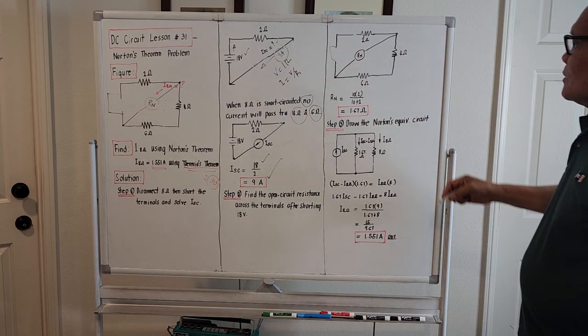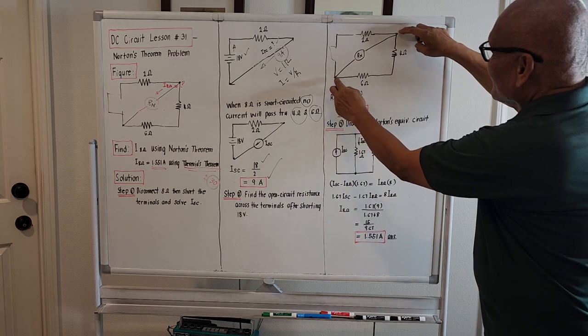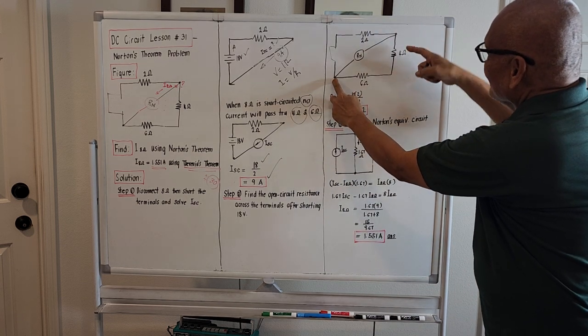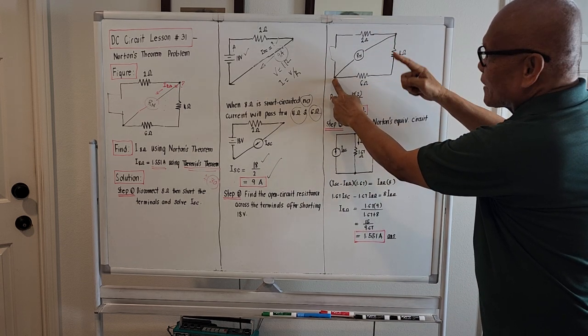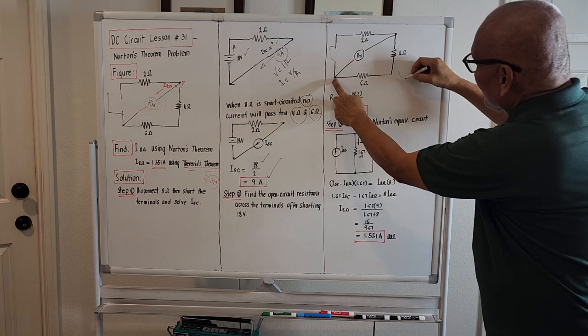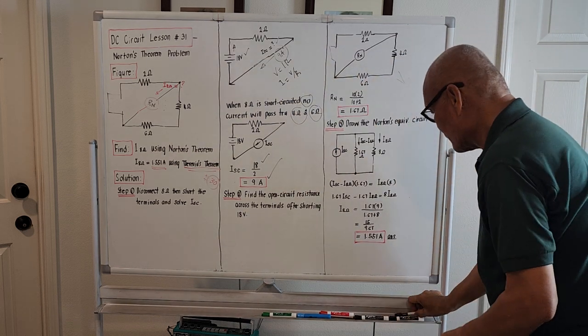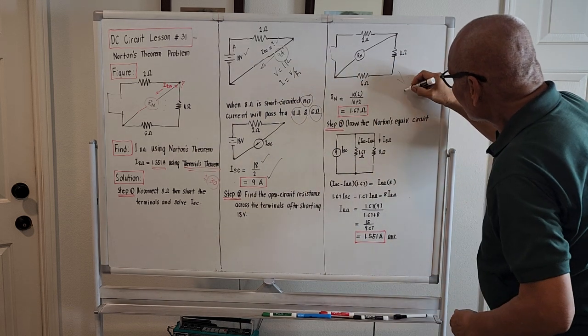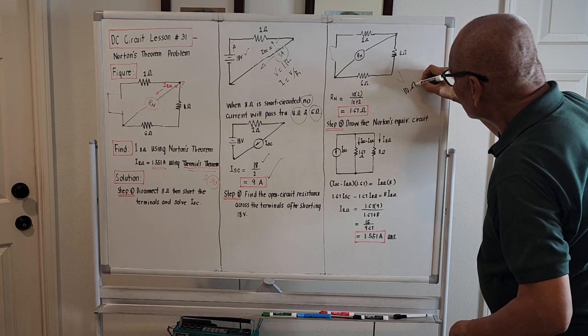Okay, so with respect to these two terminals here, this 4 ohm and 6 ohm are actually in series, so the single equivalent will be 10 ohms.